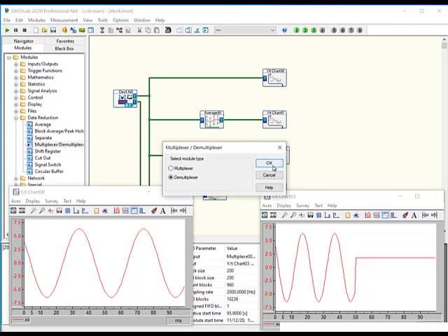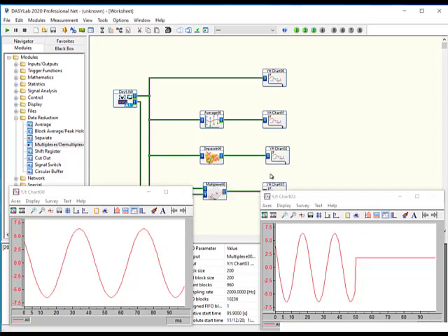And so take the number of channels that you had and take the one wire coming in and output as many wires as you had multiplexed. What this does for a particularly complex worksheet is allow you to combine multiple wires into one wire that you can then route through your worksheet and then break it apart again at another point in your worksheet. It helps manage the complexity of worksheets.